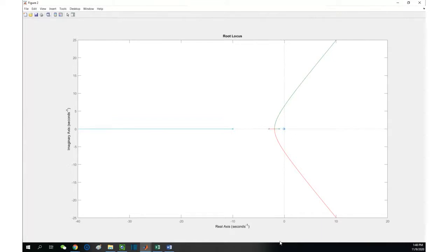You're seeing the root locus is not changing much at all. However, it's obviously not the same as before. See this introduced the new 0 here? Very tiny, very small, but it does exist. It's not exactly the same as before, but it's not changing much either, right? This justified the previous conclusion. Okay, PI can basically keep the original root locus if you're designing your 0 close to the origin point. This is a new root locus.